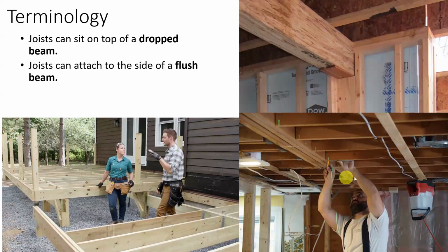So now we've got our joist. Here's a wood I-joist up above, and it's being supported by an engineered lumber beam. That looks like a Paralam to me. It's an engineered lumber piece. These are wood, looks like 2x10s or 2x12 floor joists, and they're being held up by another wood 2x10 or 12 built-up beam, right? So there's like 4 layers of 2x12s that are nailed together.